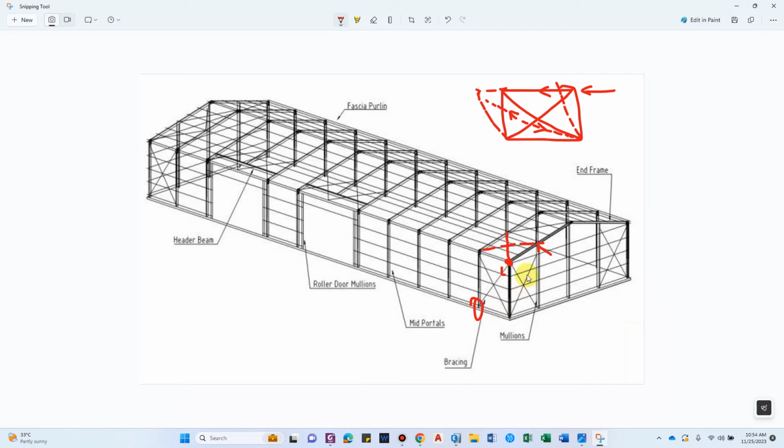So this is how the bracing works. The force is applied to a node, gets transferred through the strut, and with the nodal force resolved, so we are just resolving the force, that force comes back to this bracing, and again at this point the force gets distributed to the other bracing and finally comes down to the footing. So whatever force is exerted on this face comes directly down to the footing due to the bracing action. That is how the lateral stability along this direction is considered.